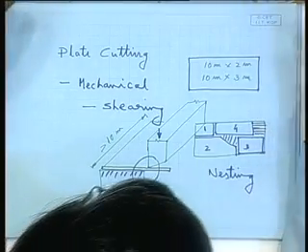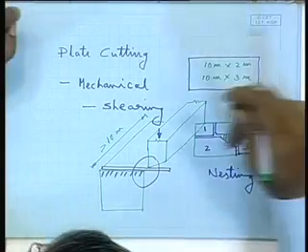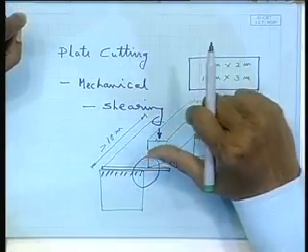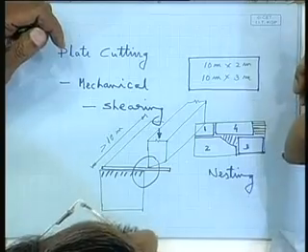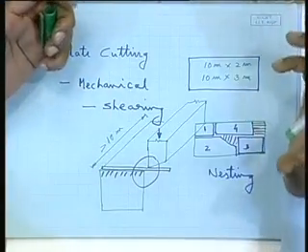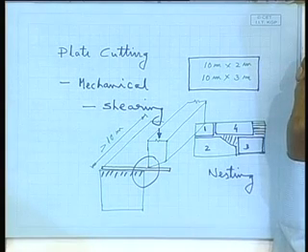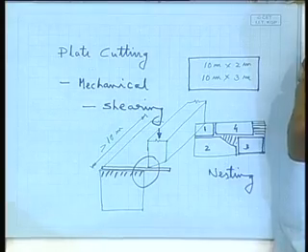The third advantage is that it is a so-called cold process, meaning no external heat is applied. So, there is no thermal effect on the plate. What could be the thermal ill effects? It could add to distortion, it can distort the plate, and it could change the metallurgical parameters. It can change the microstructure, thereby changing the properties at the cut edge. Those things are not there, because there is no heat involved. So, this is a quite efficient and advantageous method, but it has a great drawback.